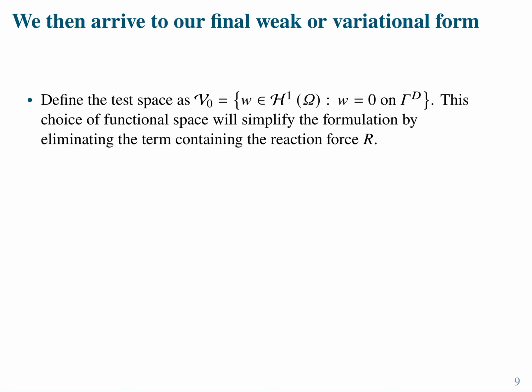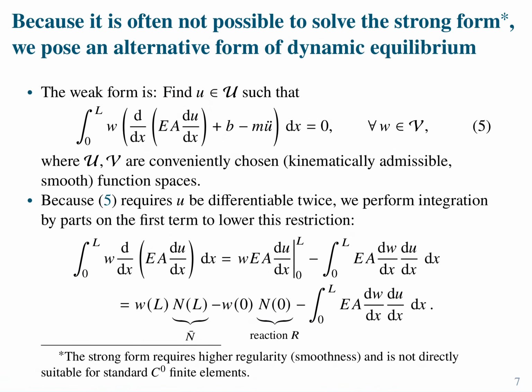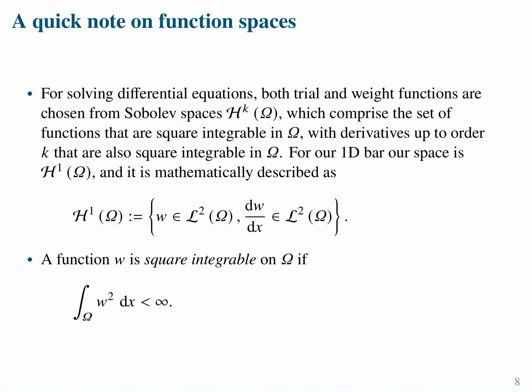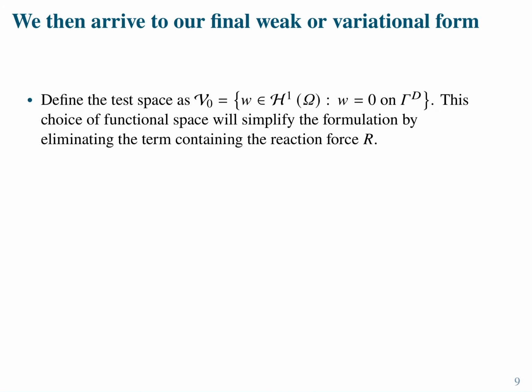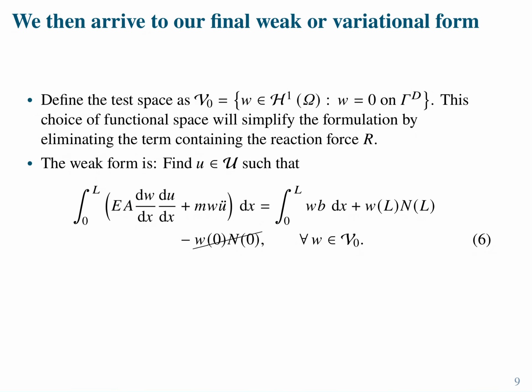And why do I do that? Well, if you look at the previous equation, remember this was a reaction force. But if I make this function equal to 0, what happens to the reaction term? It drops. I don't need to deal with the reaction anymore in the formulation. So this is a simplification that we normally do in finite element analysis. Otherwise, you have to add another equation to be able to deal with the reaction in the formulation, and we don't want to do that.